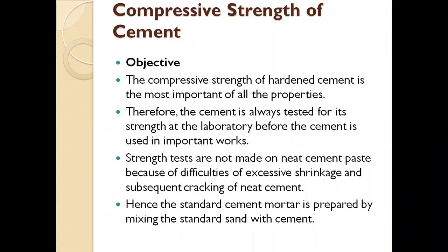Hence the standard cement mortar is prepared by mixing the standard sand with the cement. So while testing the compressive strength of the cement, we have to add sand to the cement. We prepare the cement sand mortar to take the strength of the cement.